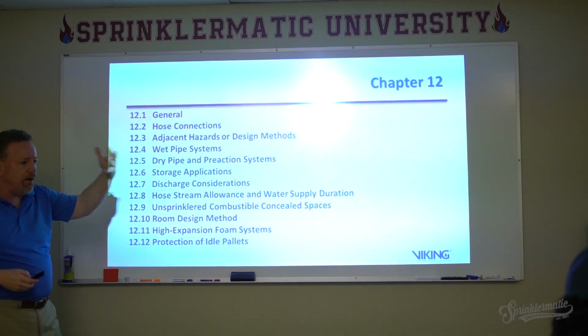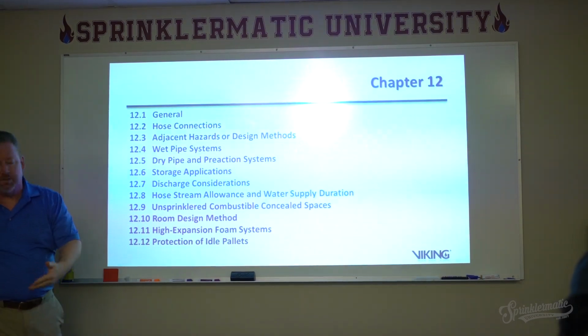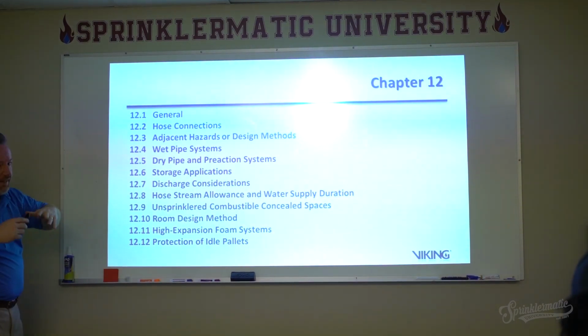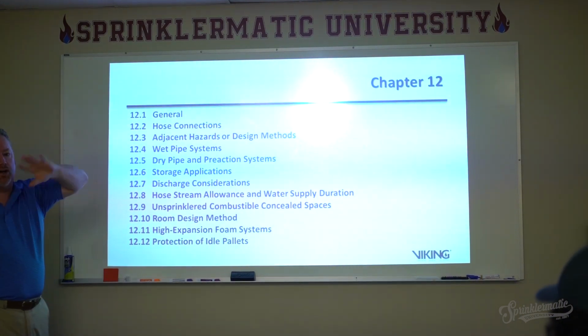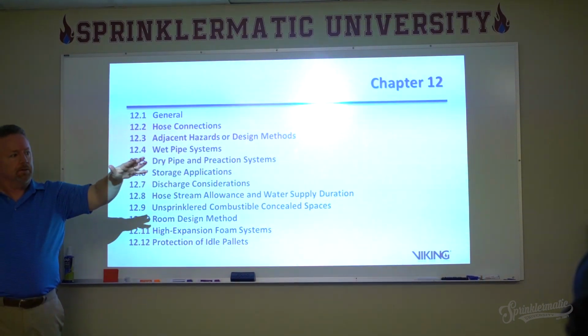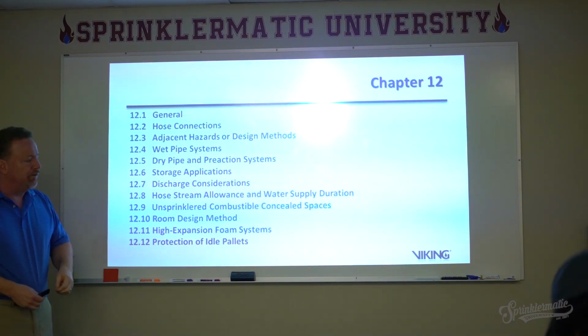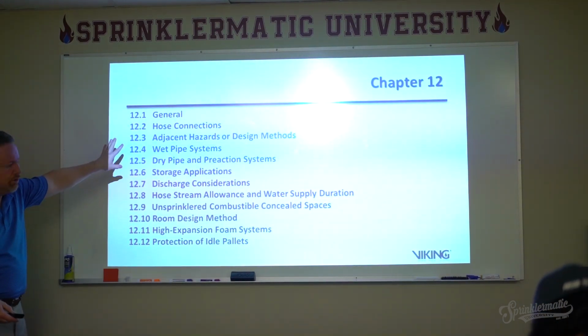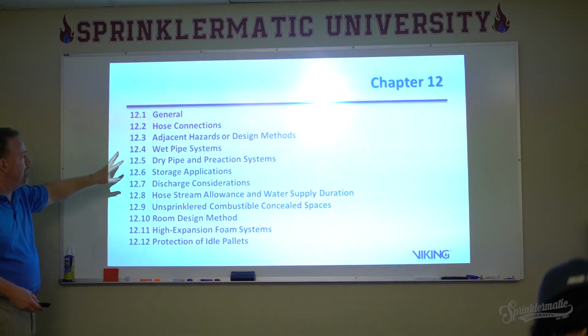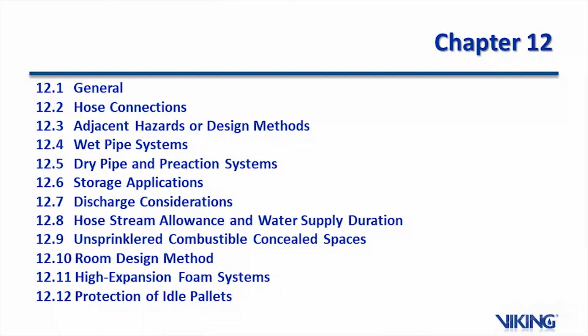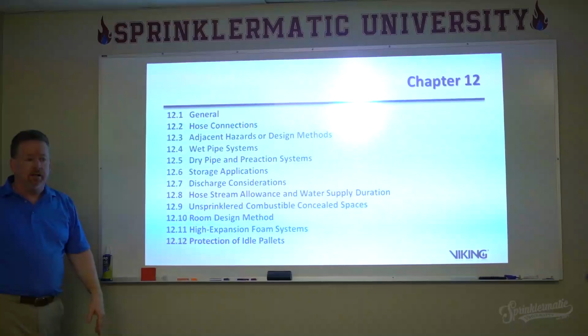Chapter 12, now we get into some specifics. We're not going to get into all of these again. That's a 2.5-day program. But chapter 12 is the general chapter that covers all storage occupancies. You have to comply with chapter 12 when you're protecting storage occupancies. That's your first stop. Whether it's the hose connections, adjacent hazards, wet pipe systems, dry pipe systems, pre-action, all of this here, you visit chapter 12 first. Okay?